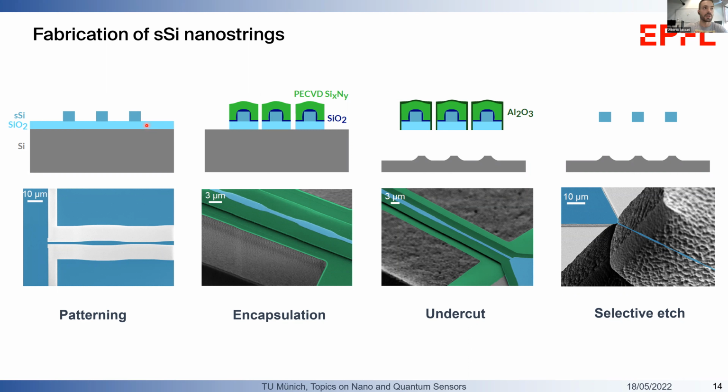If you started out with several microns of sacrificial oxide, you would be able to undercut the strings simply in vapor HF, for example, and then the fabrication process would be extremely simple, just a couple of steps. Vapor HF also doesn't present stiction, so it would work out perfectly. But we started out with this particular wafer stack, so we worked with what we had.